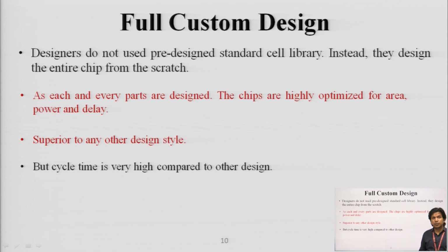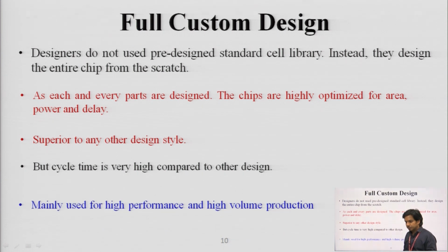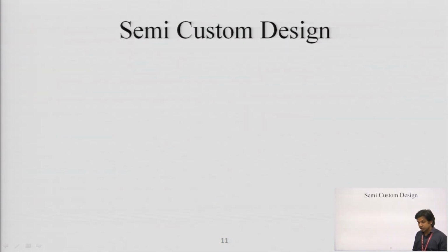As this technique uses a full implementation starting from scratch, we are optimizing each and every component, which is why this technique is much superior compared to other design styles, but it costs time; huge time is required to implement each and every component. So, this is mainly used for high performance and high volume production.